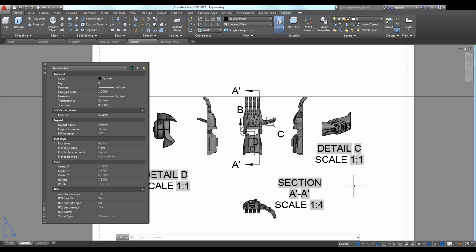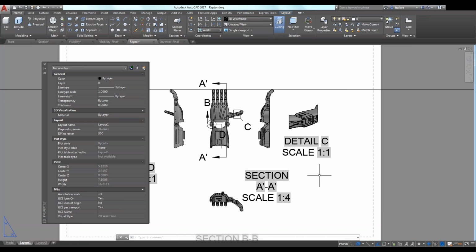Dimensioning and everything, and if you want 3D dimensioning, you'll have to use the 3D OSNAP feature. I'll start, and if you want to interrupt me, you can. All right. So you can dimension the views. You can use the regular dimension tools, and the 3D object snaps are what you'll want to use there.